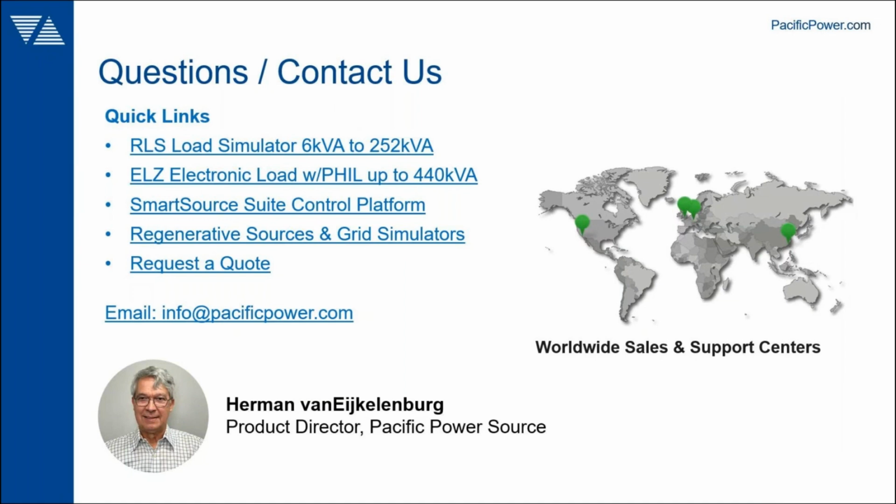Generally, when you're developing test programs or test sequences, the developers and the engineers that do that would have to have access to control the output and or the load settings to determine what is the correct way to test their EUT. And then once that has been defined, documented and programmed, you can have other people using those programs that are already debugged and written, and they can't make any changes to that and can just execute it, to perform the actual test or the burn-ins that they're supposed to do in production or test.